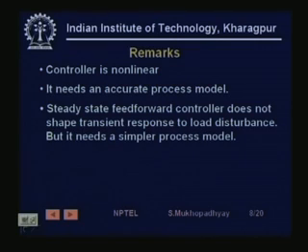And see that at steady state, if you have a step input in Ti, there will be a step change in Q, but a step change in Q may not exactly match the response of the temperature in the tank. That is, there may be some transient, that is, from instant to instant it will not be able to match the temperature.